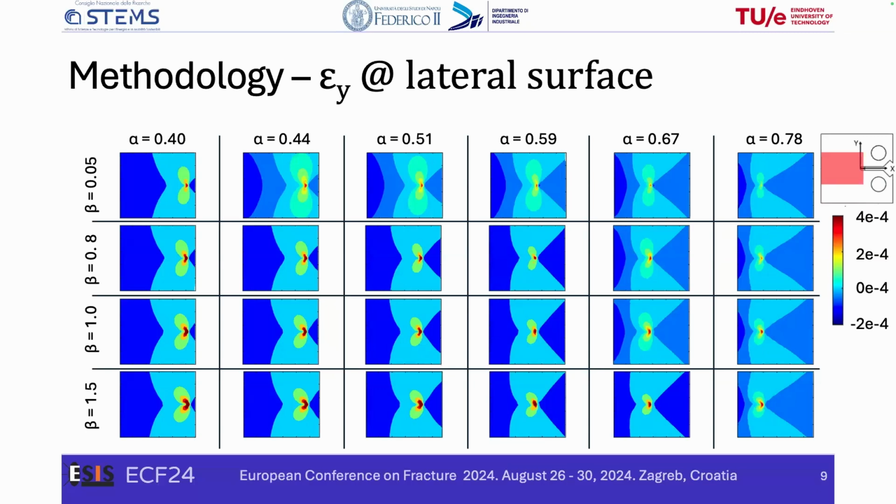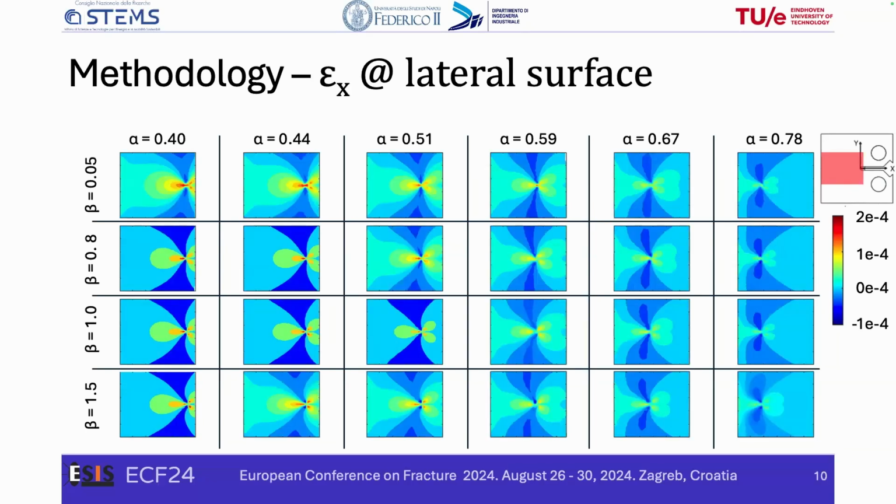On the rows, you can see different crack tunneling conditions, and in particular, you can see that for each crack length, the beam shape increases its sides and bends over itself with increasing severity of the crack tunneling. And this provides a reliable pattern for classification of the different scenarios. Additional information is provided by strain along the X direction.